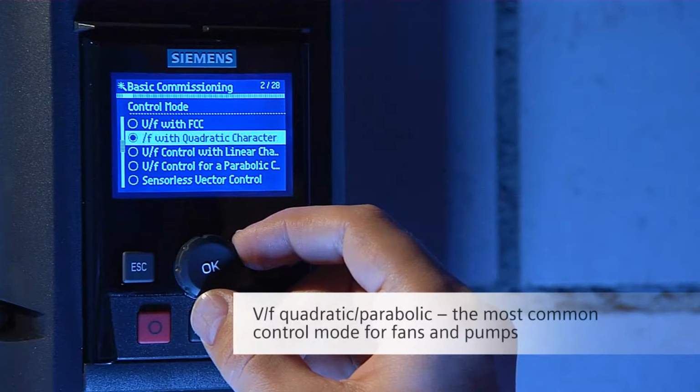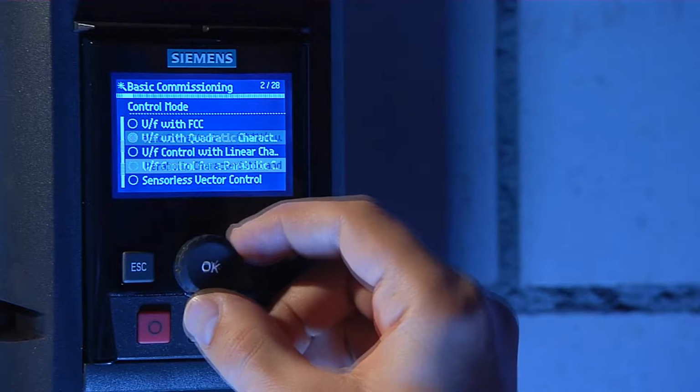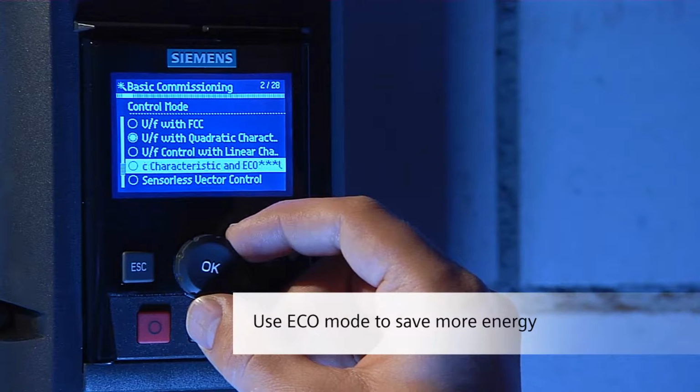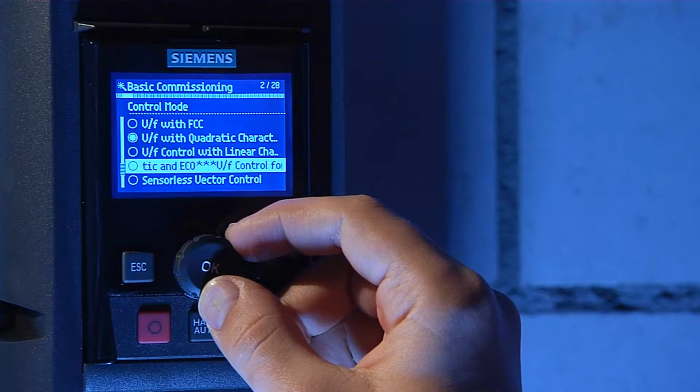V2F with parabolic characteristic, the most common HVAC control method, is already pre-selected. Use V2F parabolic with eco mode for saving even more energy. In this mode, G120P will reduce the output voltage as much as possible without reducing the speed of the motor.